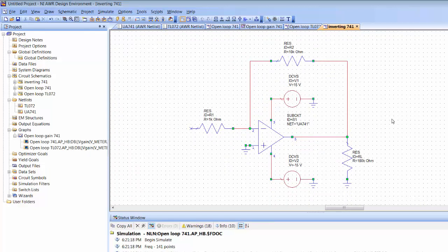And what we need to do, of course, is have a voltage source. Press Ctrl+L and ACVS, and then we'll put a voltage source right here, and we connect it to this resistor, and then put a ground connection down here. Again, we have to be very careful with what voltage level we put in here. In this case, we can go a lot higher, but bear in mind we have a gain of 10. So if we have a voltage of 1 volt here and an amplification of 10, then we'll have a 10 volts peak voltage at the output. Personally, I'd quite like to take this down a little bit, and I'll use an amplitude of 0.1 volts instead.